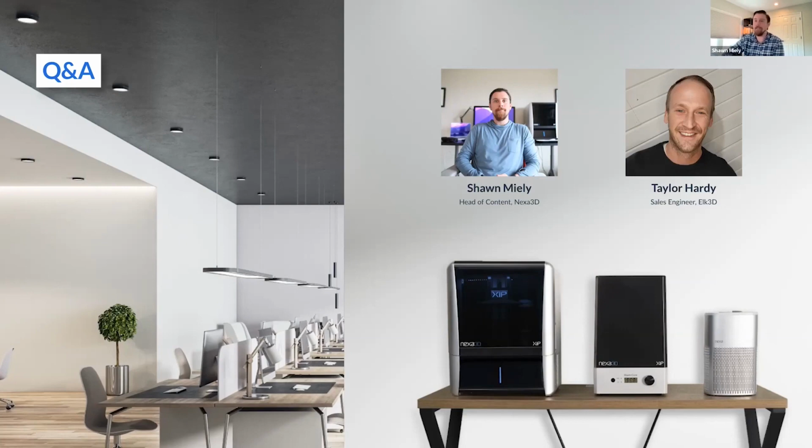I actually haven't used other MSLA printers before, but I have seen parts by comparison. I know with the zip, you get about a 52 micron pixel size, but then we have anti-aliasing technology built into that. So you get what Mike likes to refer to as sub-pixel resolution, where you can basically turn it down to like a quarter of a pixel. That's all automated on the back end, so it creates smoother surfaces, finer feature detail, stuff like that.